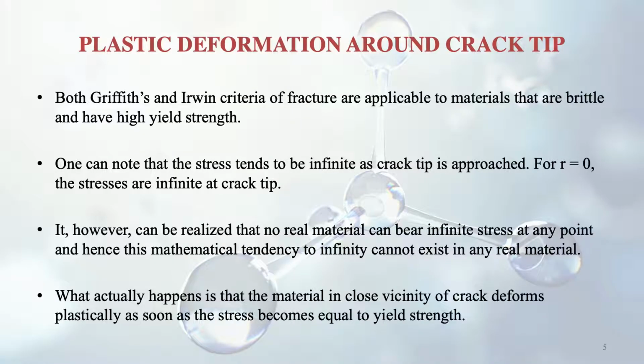What actually happens is that the material in close vicinity of the crack deforms plastically, like you have learnt in the previous sessions about plastic phenomena. Up to the yield point, the material can come back to its original position after deformation, but after the yield point it becomes plastic, meaning it cannot come back to its original position, and it will retain a certain amount of deformation. So I am reminding you of that plasticity here. That's what happens, and so there is no infinite stress.